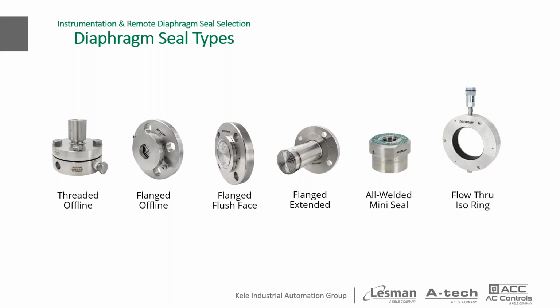The significant volumetric displacement for these seals allows for multi-instrument configuration options where you can install a gauge, a switch, and even a transmitter, all on a single seal. We'll see an example of that in just a moment. The full bore or zero pressure drop design of these seals make them the perfect candidate for measuring pump discharge pressures. There are two other seal types I'll mention here, both saddle seals and button seals. We do see plenty of each, but they are less common than most, and we've only got so much time today.